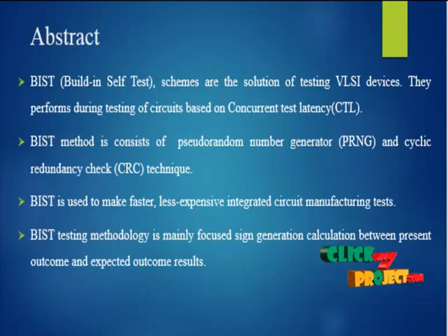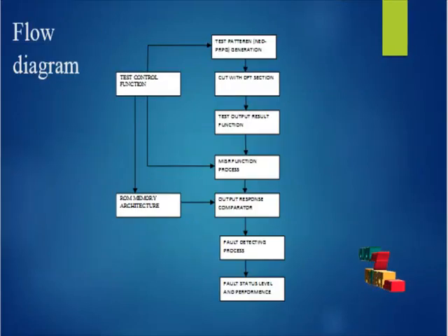We implement the BIST algorithm. We activate and select individual cells for each test step, and then we extend the test column address from 4 bits to 7 bits. Let me show our process flow diagram.